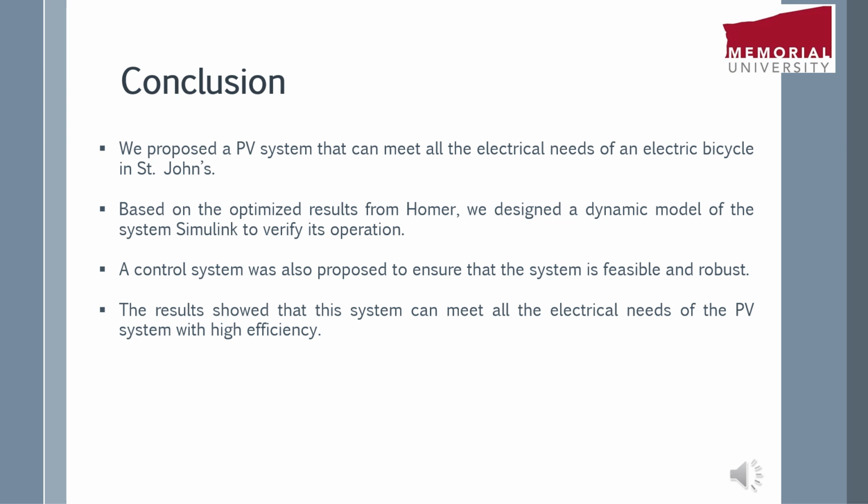And then we also presented the results for all these control system simulations and the Homer results as well. We also ensured that our system could be very protective in the sense that it could withstand over temperature, over current, and over voltage conditions using relays that are activated whenever these conditions occur.